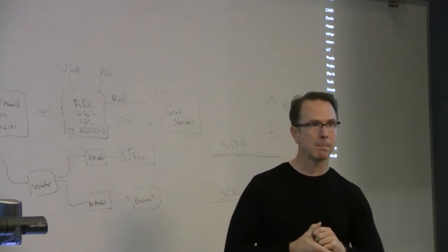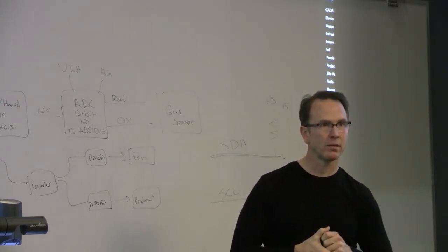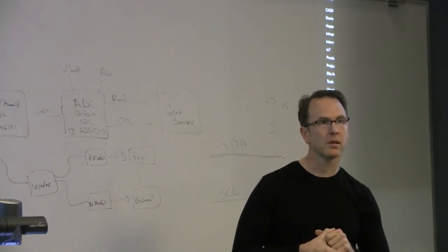If you have well-behaved devices that follow the I2C spec, they're open drains, so they're only ever pulled to ground or floating. So in theory, the source voltage shouldn't be coming through on those lines, so it should be safe.